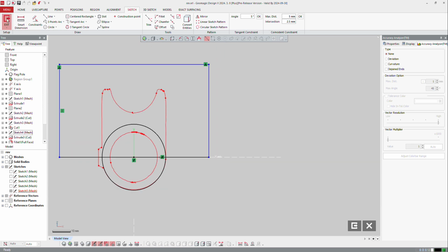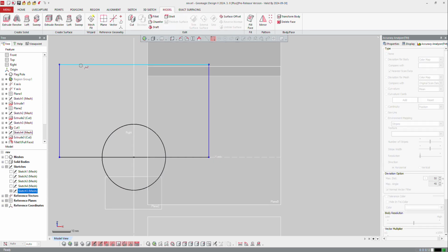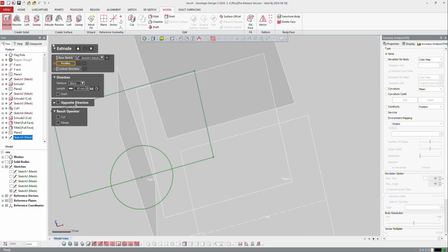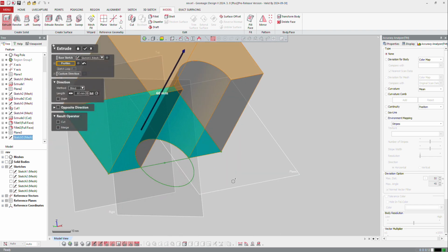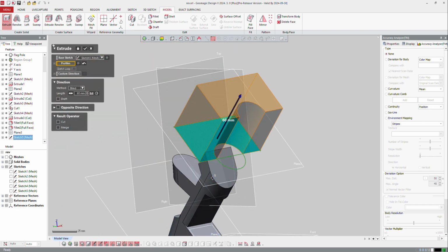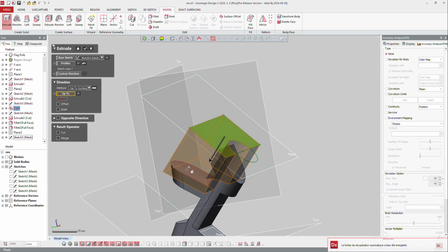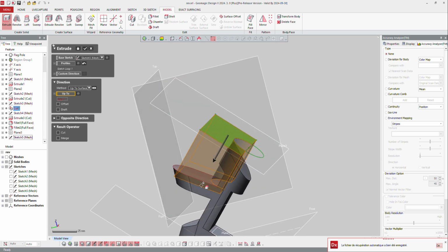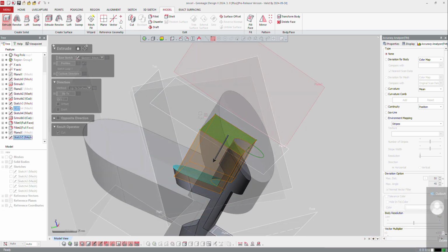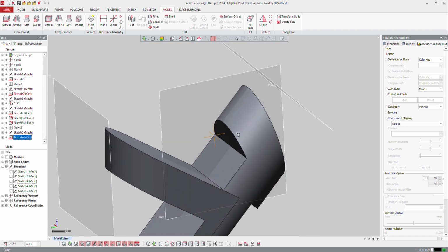It doesn't matter again. I can now right mouse click on this sketch, extrude in solid, that shape, Alt space to display my solid body, and ask the software to go up to a surface, which is going to be that one. So it's extruding up till it reached that area, and I cut the model. So you can see now it's a nice shape we got there.